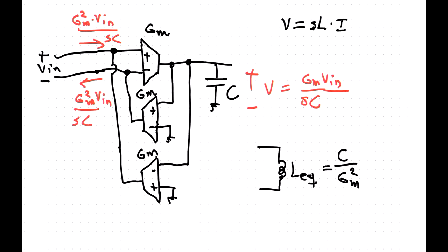The other use case for real inductors is if the frequency is really fast, because these active circuits have a finite operating frequency, and you need to be much lower than the transition frequency for the transistors. And if you want to do RF circuits or something that's high frequency, you can't do that either. So those are the two use cases for inductors: power switching or power circuits, or high frequency.